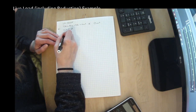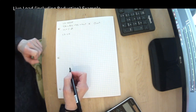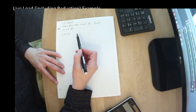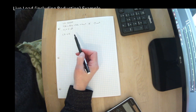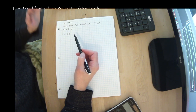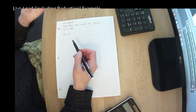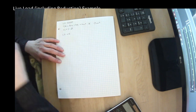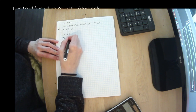Let's look at level 3 to level 4. So level 3 to level 4, it is carrying level 3 and the roof. We know that the roof had no tributary area and no live load associated with it. So the tributary area from level 3, well actually, let's talk about what the live load is first.